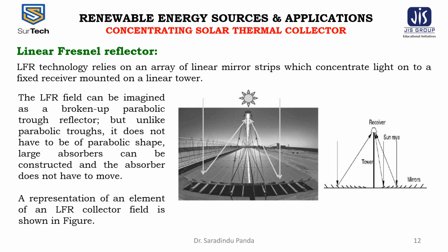The linear Fresnel reflector technology relies on an array of linear mirror strips which concentrate light onto a fixed receiver mounted on a linear tower. The LFR field can be imagined as a broken up parabolic trough reflector, but unlike the parabolic troughs, it does not have to be of parabolic shape. Large absorbers can be constructed and the absorber does not have to move. A representation of an element of an LFR collector field is shown in the figure.